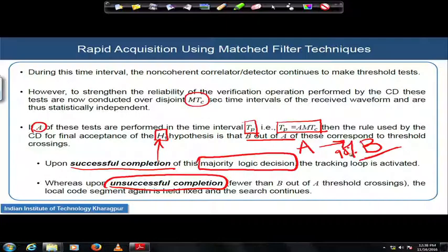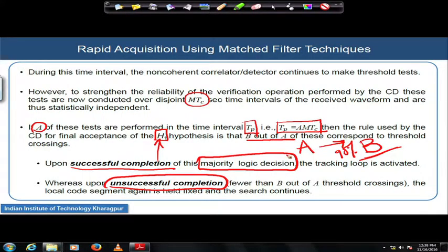That is a measure you can feed back from the final demodulation and detection of the bits, to readjust the level of this capital B inside the synchronizer, inside the CD, so that performance can be further improved.